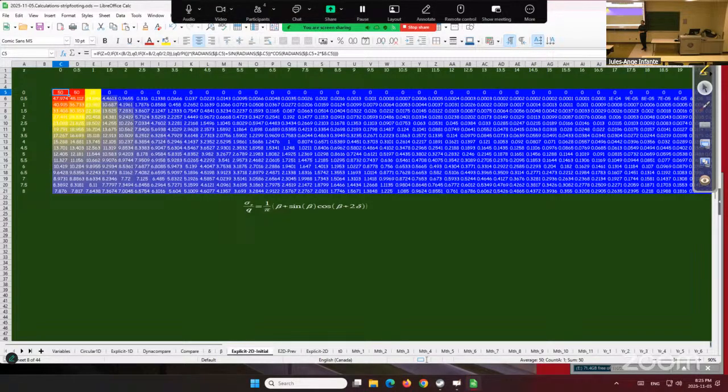You're saying computed at every point along the surface? Well, you just need to have a number of points X and Y that define the entire circle. Right? And at each point, you assign a value of a load. So basically the stress times the area of the little squares, right? So you have now point loads, a finite number of point loads, describing the shape that you want.